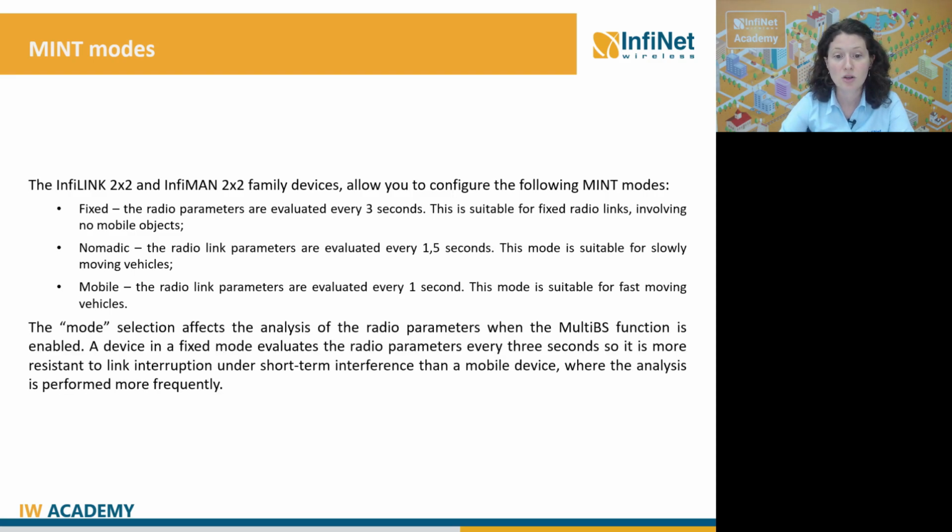The mode selection affects the analysis of the radio parameters when the multi-base station function is enabled. A device in a fixed mode evaluates the radio parameters every 3 seconds, so it is more resistant to link interruption under short-term interference compared to a mobile device where the analysis is performed more frequently.